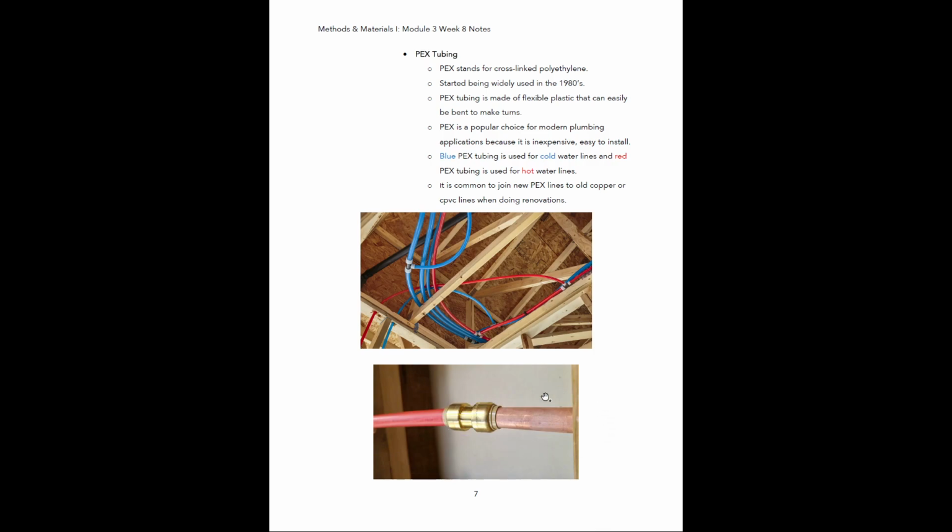You'll take the old plumbing, and then when you have to add on new fixtures to the building, say you added a new bathroom somewhere in a house and you have to run new plumbing to the existing copper plumbing that's there, maybe you want to save some money and go with PEX. Well, you have to have a way to tie into the existing plumbing that's already there, and that can be easily done with PEX with these special connectors. So you'll see that a lot in renovations.